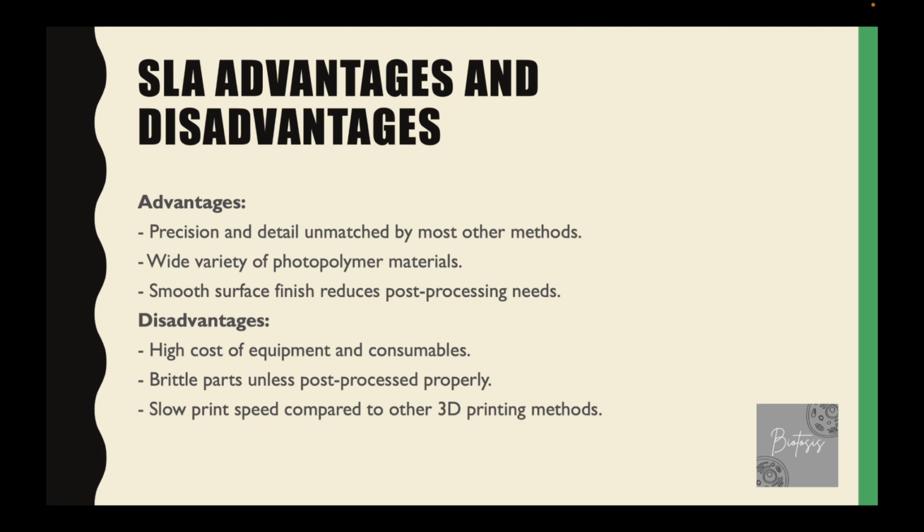Very little post processing is required after this, but the disadvantage is the cost, obviously, and the brittle parts unless post processed properly, right? And slow printing speed. The stereolithography printing speed is comparatively slower than the other printing methods.